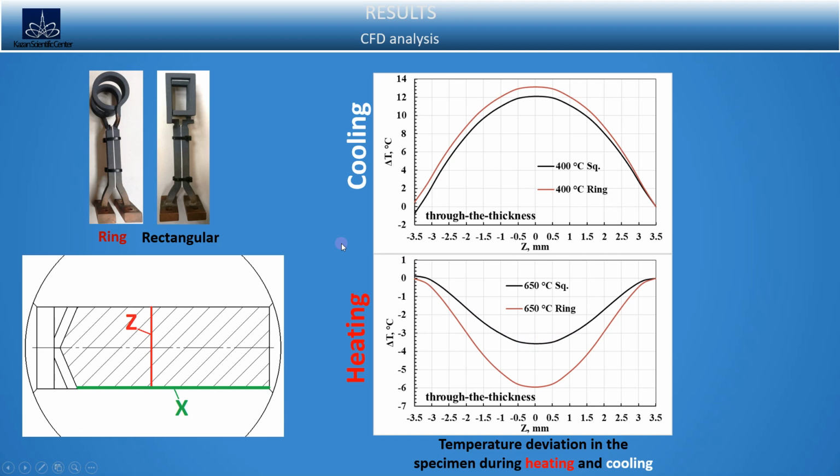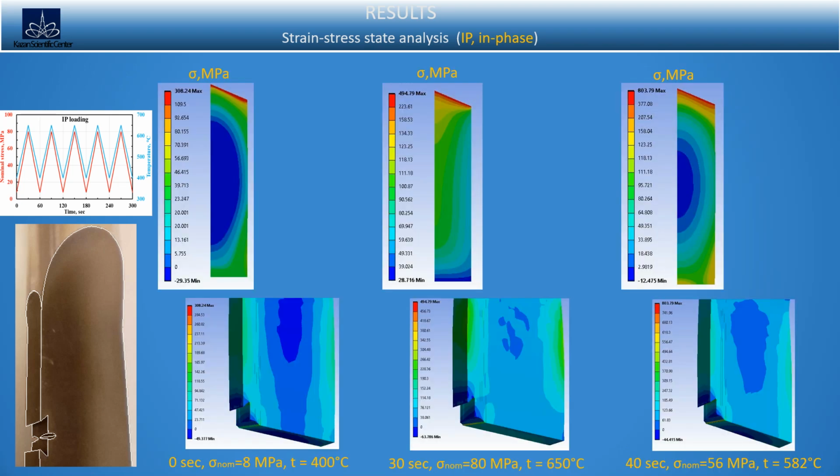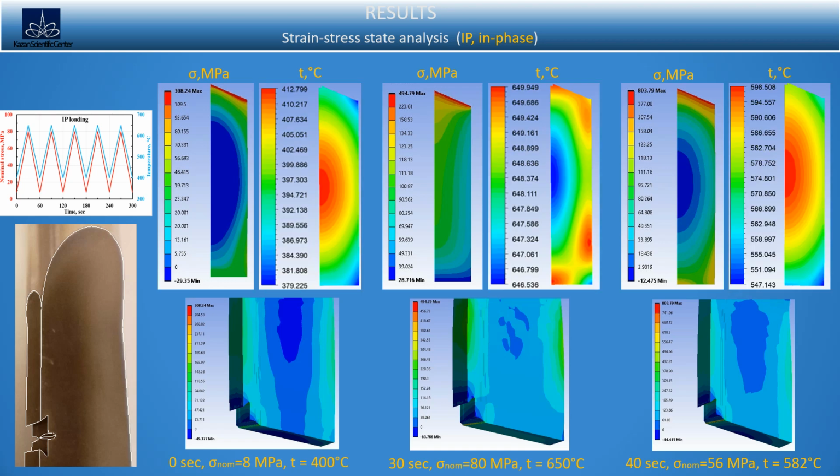The structural analysis shows the following interesting features that are not possible to measure during the test. The figure shows the distribution of normal stress and temperatures in the specimen plane. In the most heated areas, thermal linear expansion leads to compression during nominal expansion. At the same time, around overheated areas, less heated and less expanded material takes the full nominal tensile load.